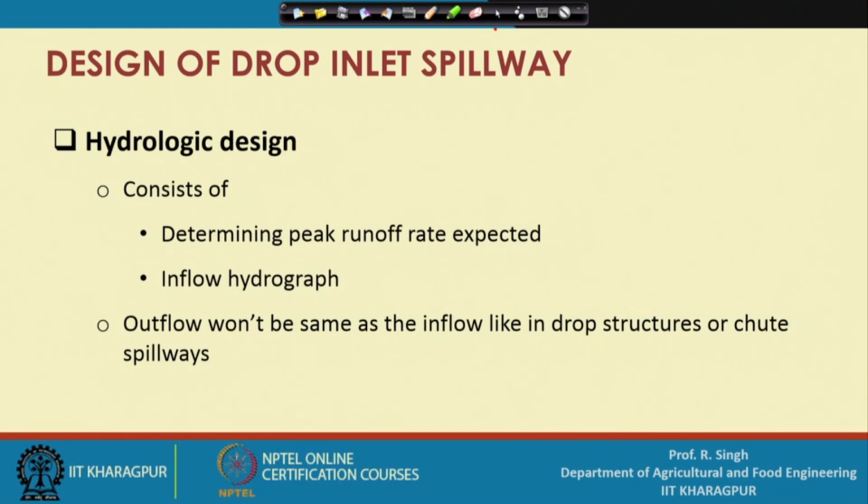Now, hydrologic design. What we do here consists of determining the peak runoff rate, that is the expected peak runoff rate, and then the second one, the inflow hydrograph. Outflows won't be the same as the inflow, like in a drop structure or the chute spillway structure. That is why we have to design both the expected peak runoff and the inflow hydrograph.